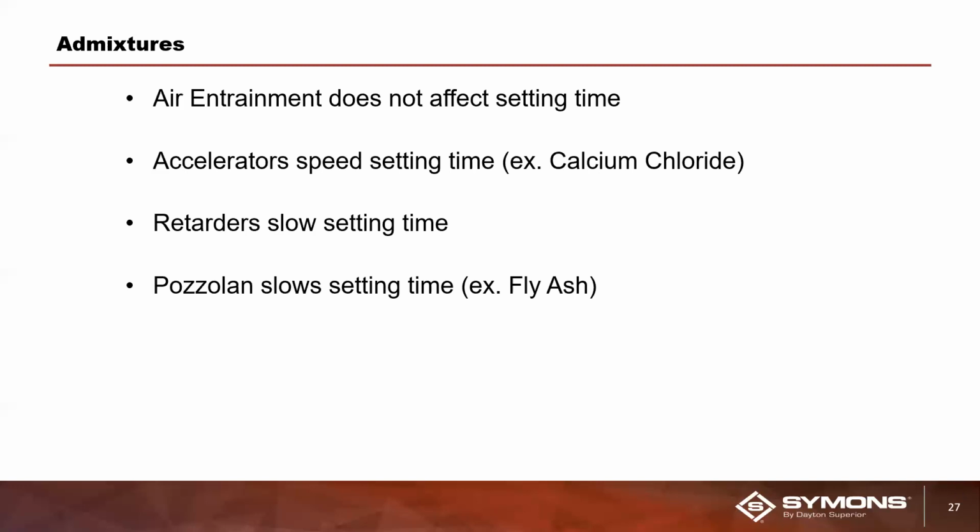Air entrainment does not affect the setting time. Accelerators speed the setting time. Calcium chloride is used a lot of times by masons to speed up the concrete that they use to set their blocks and so forth. Contractors typically will also use calcium chloride to help speed up the setting time. Retarders typically slow it down.